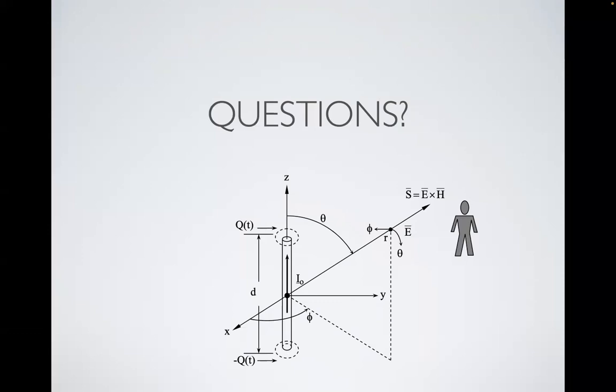Okay, so let's start with elevated. Calculations and demonstrations have been done that show that you can get away with as little as 2 radials if they're tuned and above the ground, where above the ground is probably a couple of feet, maybe 6 feet off the ground at a minimum. And most of the energy is not going into the dirt at that point. And those have to be tuned to the length, to the frequency of operation. If they're on the dirt, they're going to be detuned anyway, so the length doesn't matter as much.